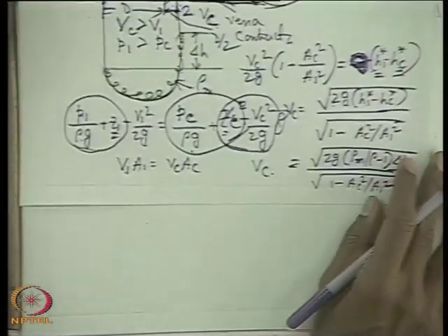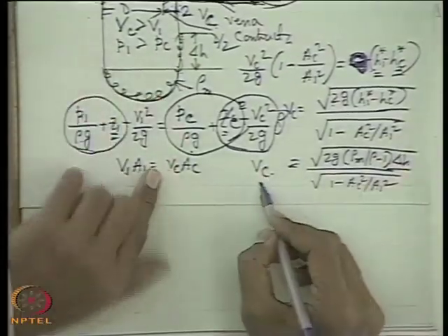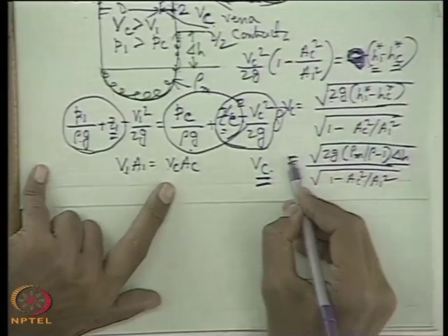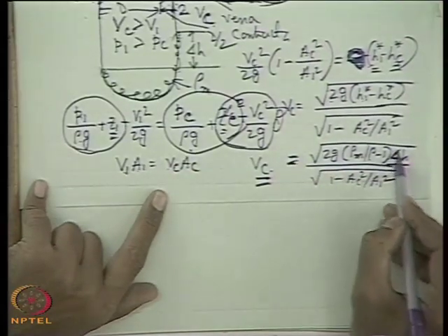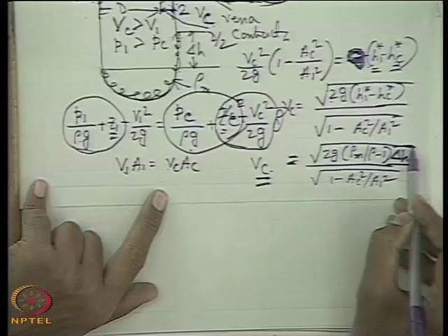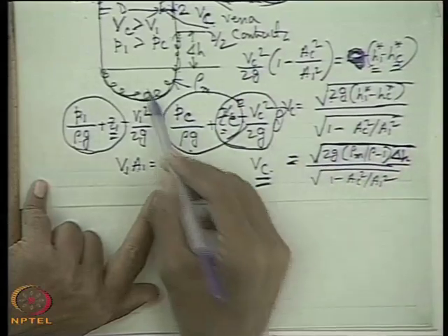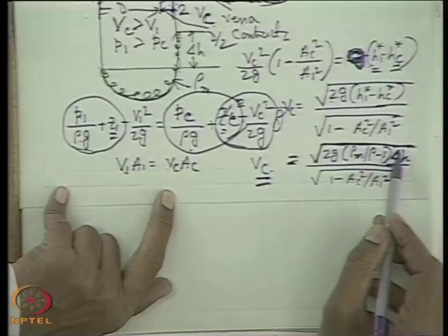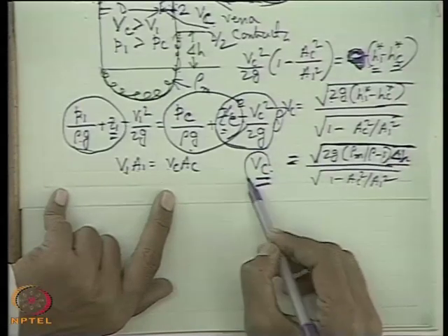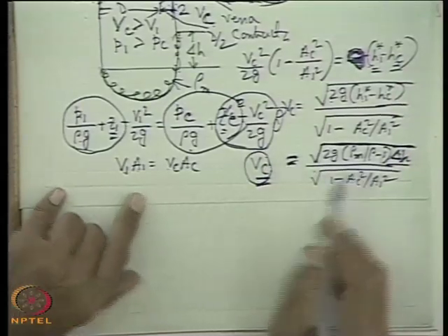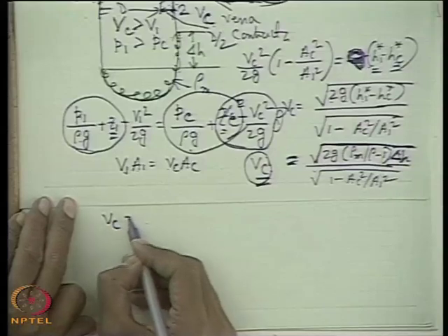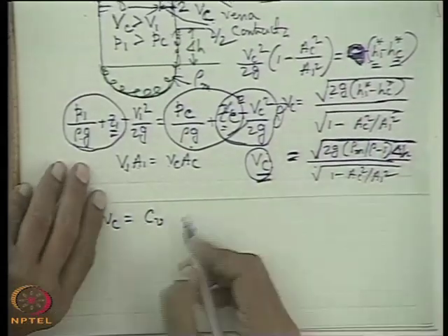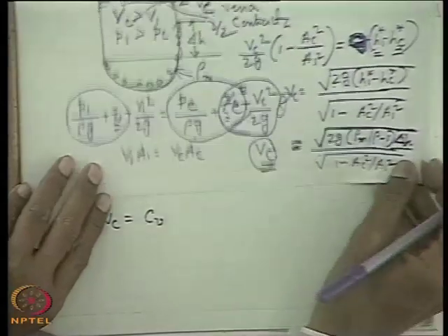Now one step further, with the same logic, here itself I multiply with a coefficient. Why? Because if I substitute delta H from the practical measurements for a real fluid, then this is more than what one can expect for an ideal fluid. So Vc estimated is overestimated. So Vc is corrected with a coefficient, known as the coefficient of velocity.